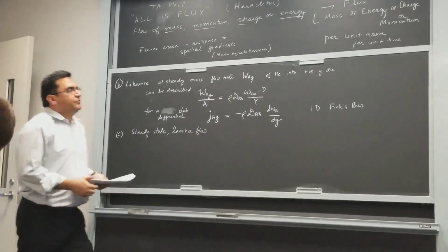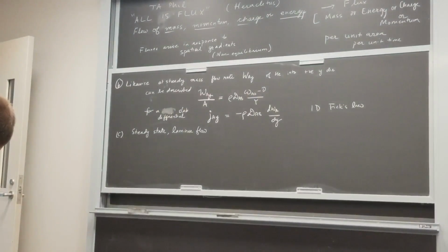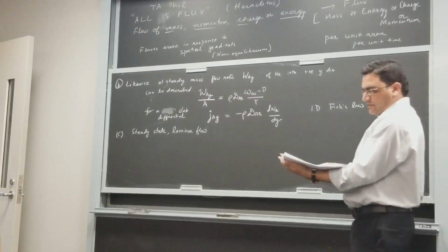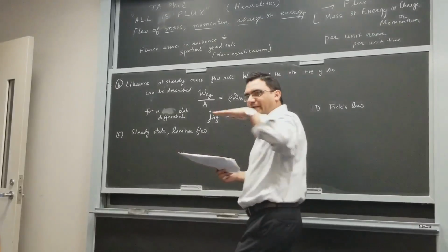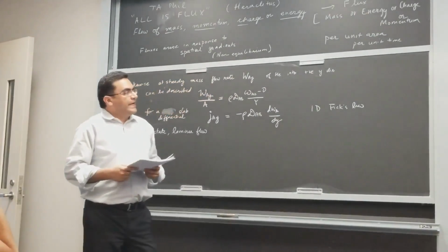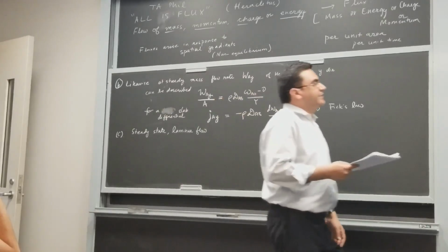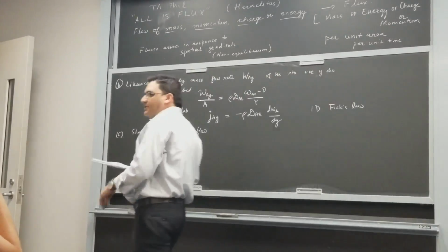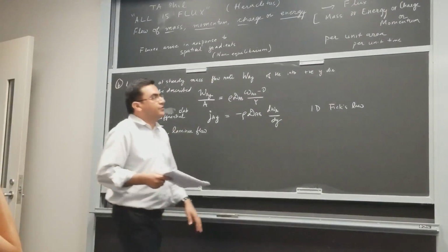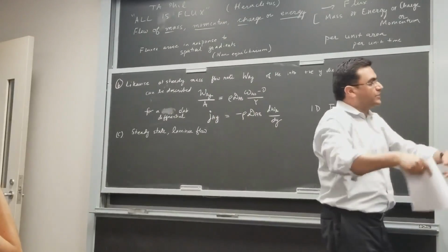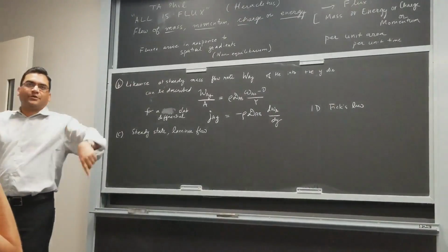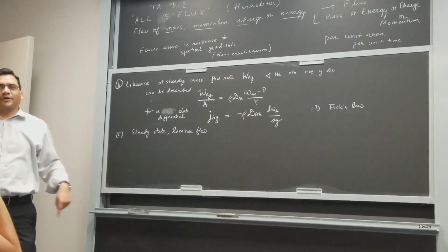Why is it called laminar flow? Well, if you look at it, it appears as if one layer is moving over another layer. They are all moving at different velocities. So they are laminae, because it's moving layer by layer. So it's called laminar flow, as opposed to what we'll discuss later, turbulent flow, that you see maybe when you stand on any bridge on the Chicago River. You will see the flow is not laminar, it actually is turbulent. So there are lots of eddies and vortices, and immediately you can see that if you have turbulent flow, it mixes things up very well.